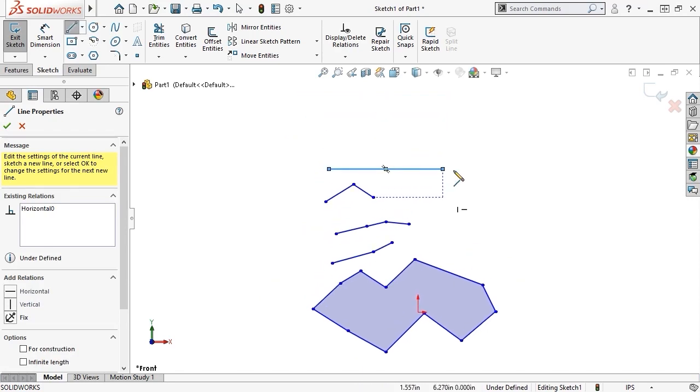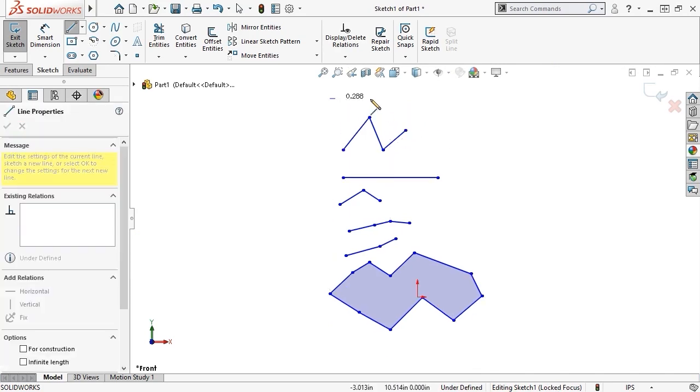It just created a single line segment. So, to sum up, using the click-click method, I can create a chain of lines while using double-click to end the chain. Or, I can click and hold the mouse button down to create just one line segment.